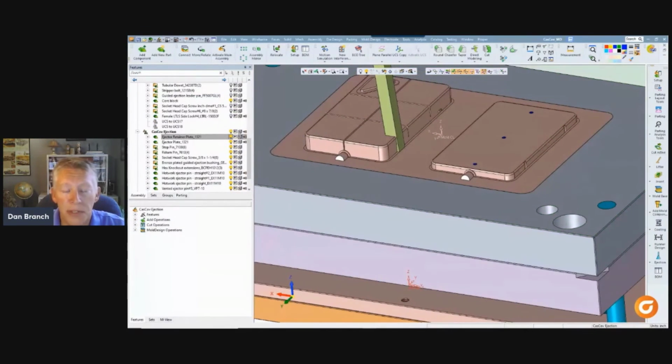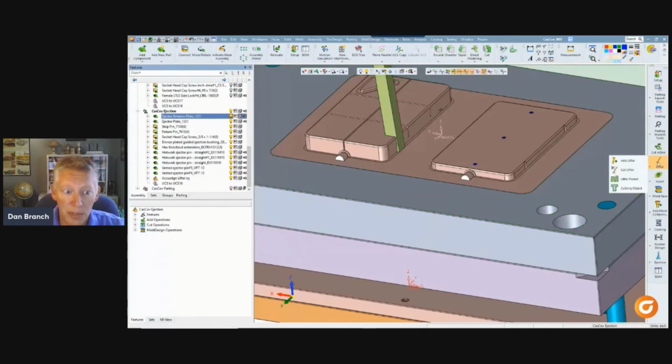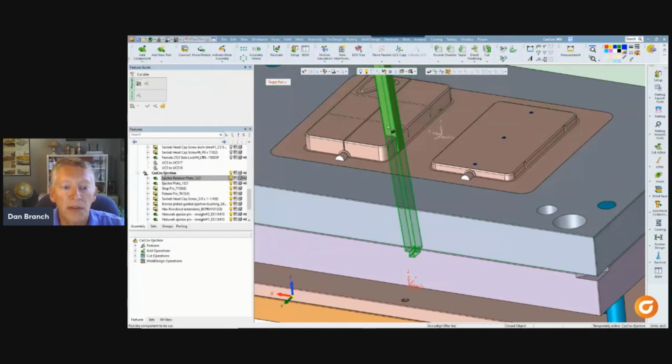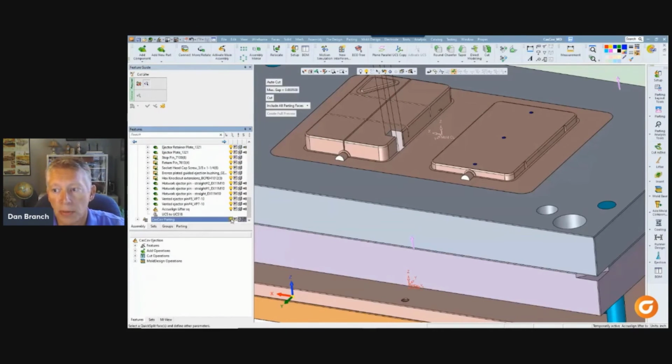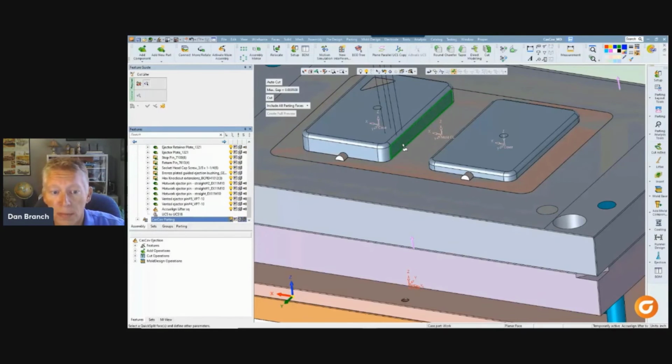The top of the lifter still needs a part shape on it. That geometry was in the core block, but the lifter pocket took it out. And that's exactly why we have another dedicated function, one made just for lifters. It knows how to get the part shape right from the original quick split part, apply it, and trim the lifter bar off.